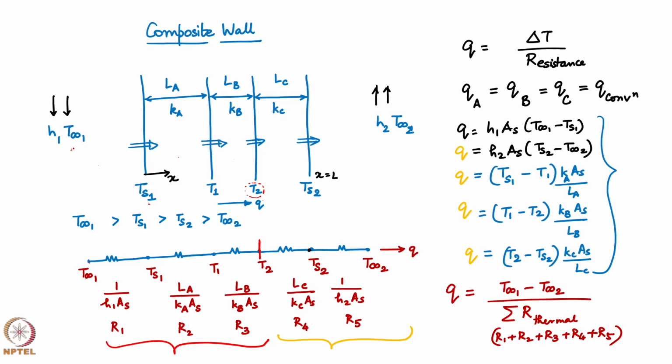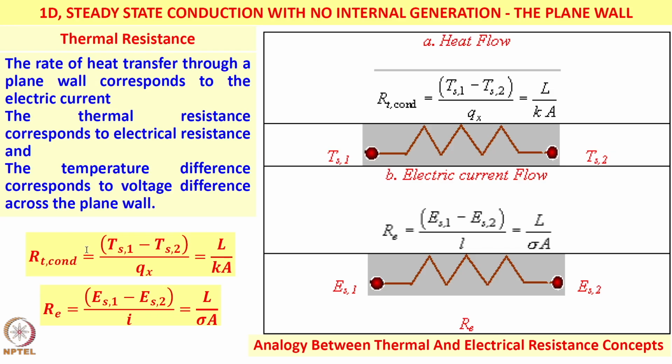You do not want to generally keep adding terms and say, oh, okay, all the resistances have to be taken because I have so many of them. No. What is the driving temperature difference you are using, resistances between that temperature difference have to be taken. Okay. So, let us just go back to this set of slides here.